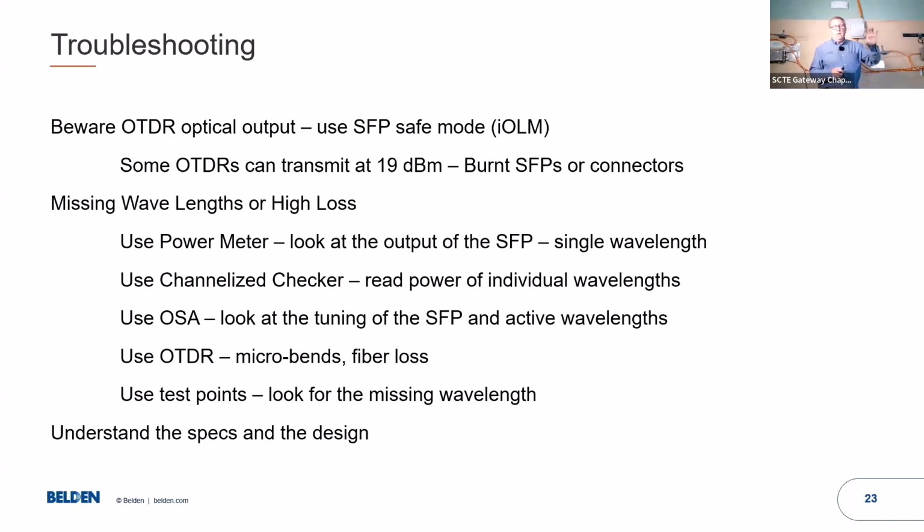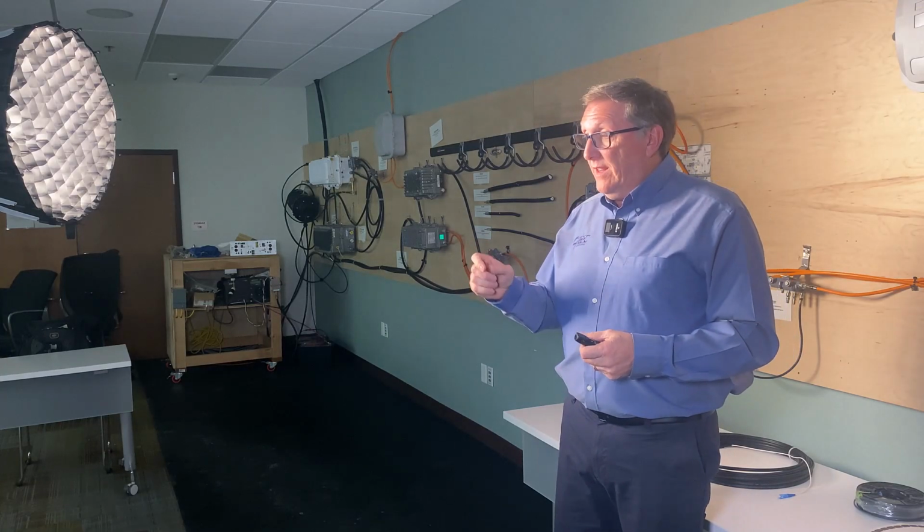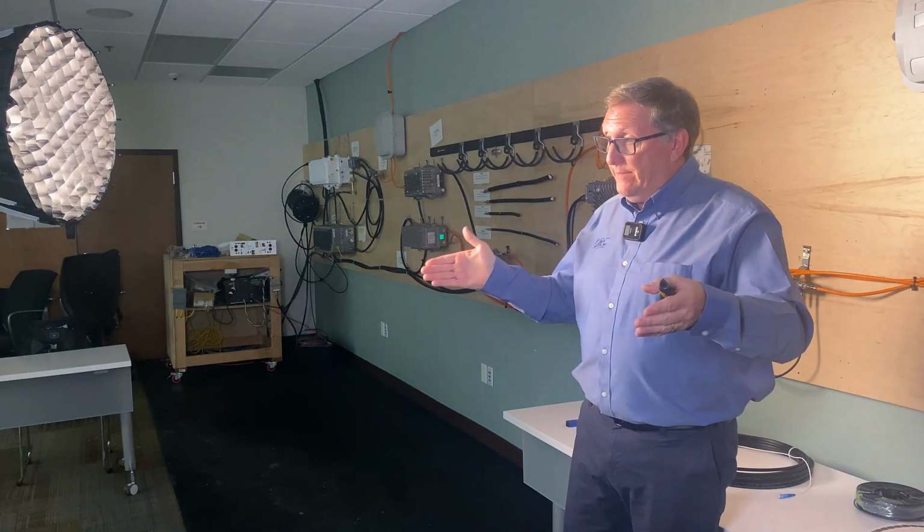They would take the input, and if you had 6 dB of light coming in and you toggled it to 850, it would just do a calculation based on if we were at 1310, now it's at 850, and it would do math and say instead of 0 dB, you got, you know, negative 0.25 or something. Wasn't really accurate, wasn't really there, especially if you had a lot of light coming through it.